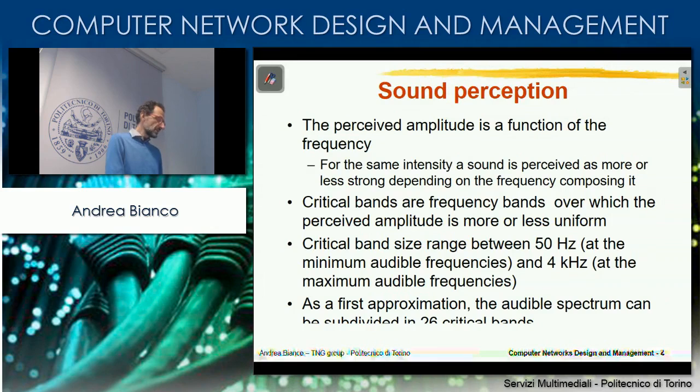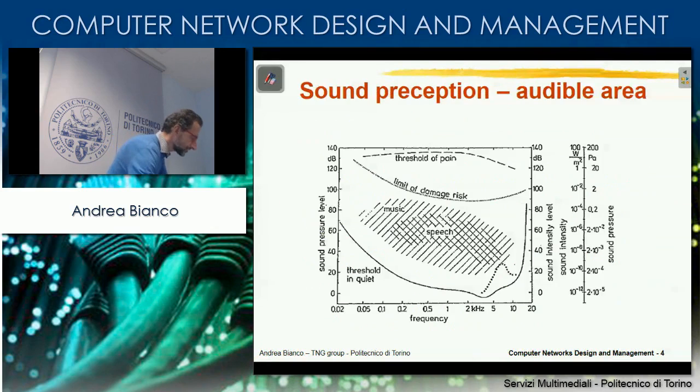And this is a sound perception graph, the sound pressure level as a function of the frequency. Okay, you see the speech is about here. This is a logarithmic scale. So the frequency band of speech ranges from here up to here, which is a little bit more than 4, you see, whereas what we can use is larger. And then we also have sensitivity in terms of the ability to receive a given power level.